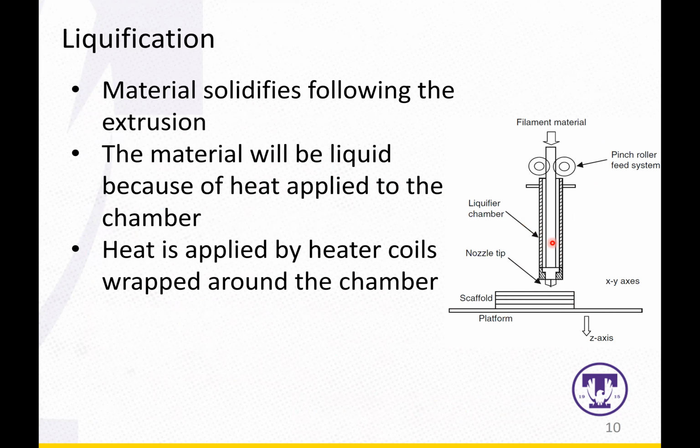And that's why thermoplastic is the most commonly used material. Above a certain temperature, those thermoplastics will be melted into this semi-solidified state, right? And actually, this heating unit is realized by using heat coils wrapped around the chamber, which simply heat up the material and melt it.